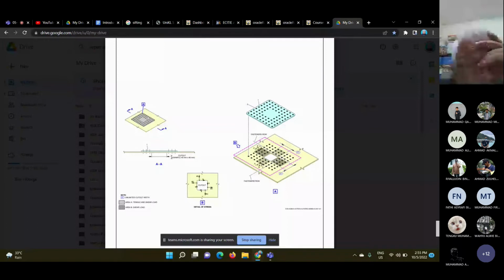However, this is a concept. If you need to repair an area where it is critical to the aerodynamic smoothness, then you just add a filler. The doubler will be inside, and then you add a filler here for you to have flush skin. So that's already different.